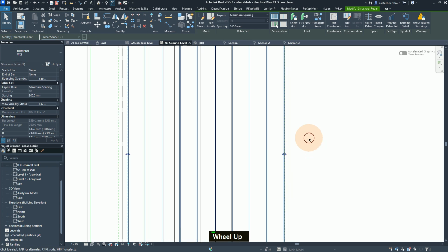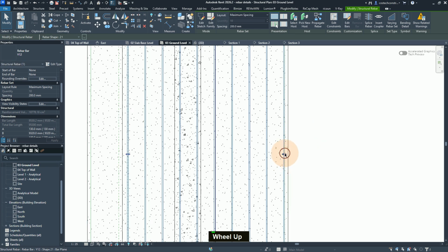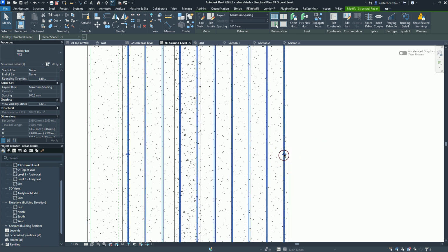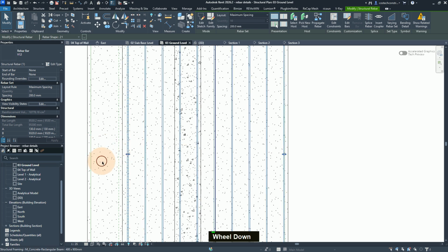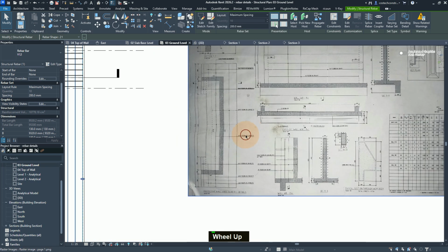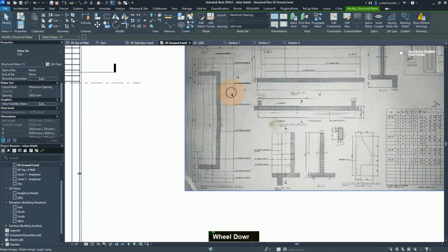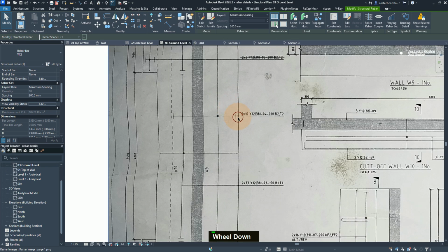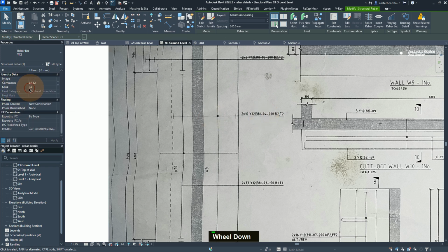Because even from the drawing, it was spanning from this part here up to here, just below, before the beam. So if we go like this, you can zoom at the drawing. And we see that this Rebar set spans from here up to here, just before the beam. The bar mark is 04, as we have input here at the identity data.